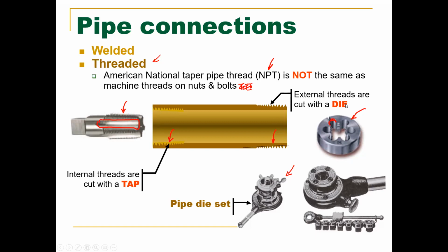It's made so that when you cut the metal, the ground parts will go into those slots. Exactly. We're removing material here, right? When we're cutting threads, we're not magically making threads appear without actually removing material. So exactly where all of those clippings go, they go into that space, and it allows you to make a cleaner thread.